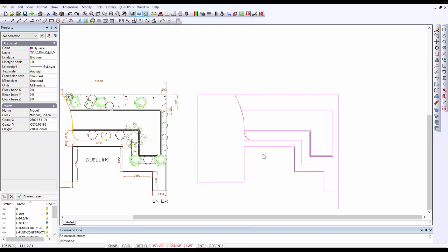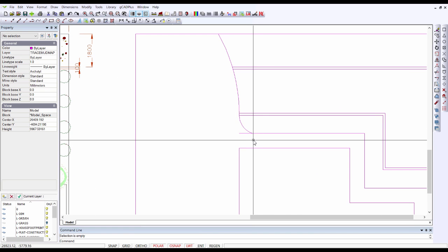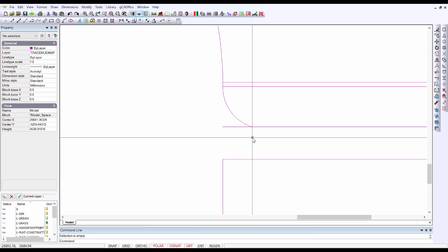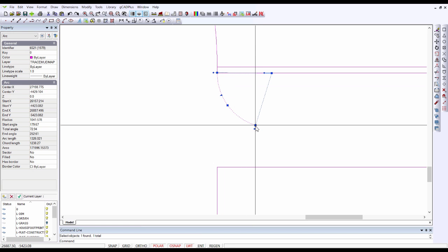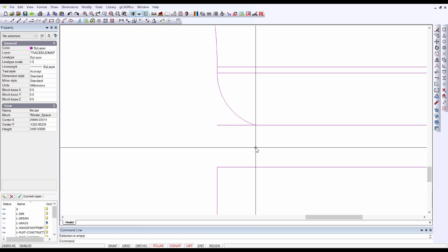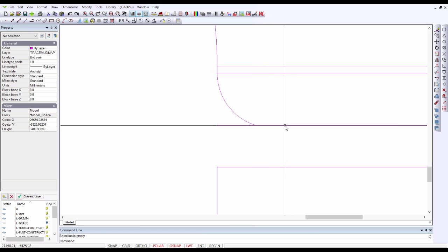We have one last problem to deal with, and that's the path extends past the edge of the arc there, and we need to blend those two together. We can't use the trim command because even though we use the OSnap near and lock the end of that arc to the line, it doesn't overhang, so the trim won't work. And I'd like to show you quite a neat shortcut.